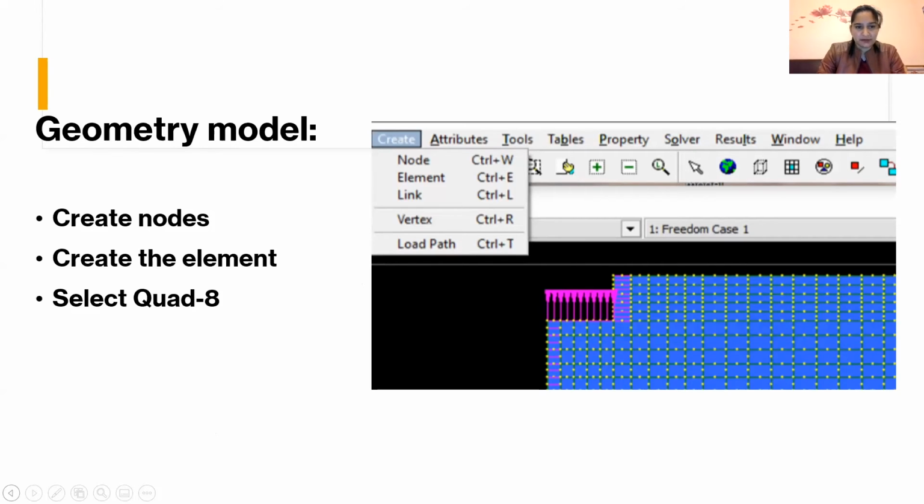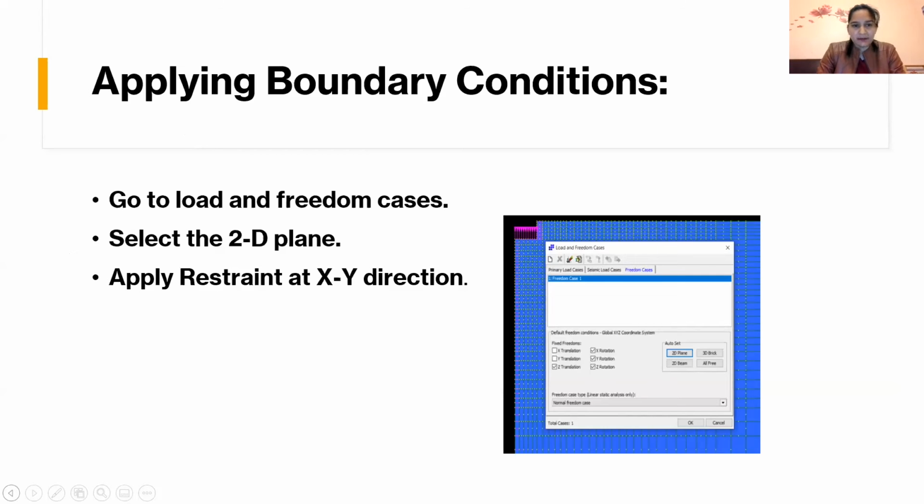So basically, when I start the foundation process, I create some nodes according to the coordinates. Then we create an element, the quad. The blue color that is shown is an element created, and the small dots you can see in the image are the subdivision of the element. Subdivision is also done very carefully. Afterwards, we also clean the mesh and clean the geometry, which is a very important step before assigning the boundary condition.